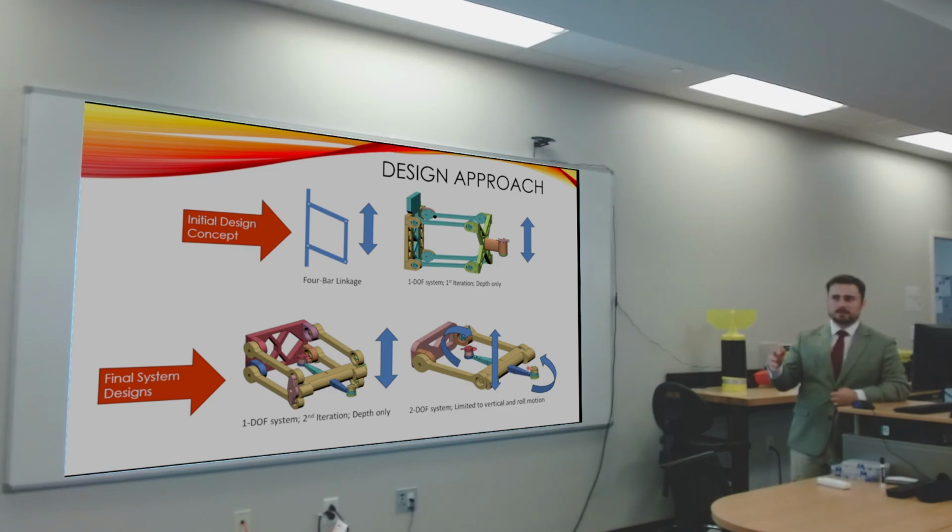But yes, beyond say 80 or 90 degrees, there does seem to be a non-linearity that occurs, because the system starts to behave in a non-linear manner. It starts to have the motors pushing a different direction, and the PID controllers kind of can't account for it, trying to push the side instead of just relying on pushing up and down. So it kind of operates within the plus or minus 70, 80 degree range, where it can orient itself, but whenever it goes beyond that, it acts in a manner that can't be predicted by the controllers. And typically, whenever it did do that, I would have to fix it by hand. So I didn't release it to behave in a non-linear manner past that.